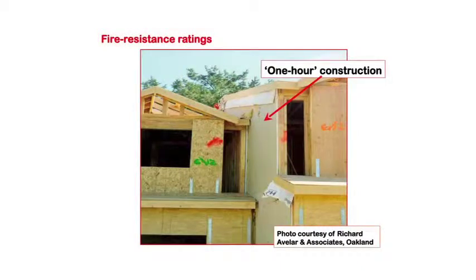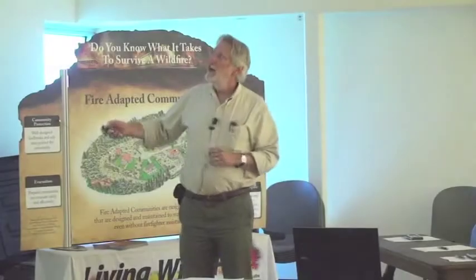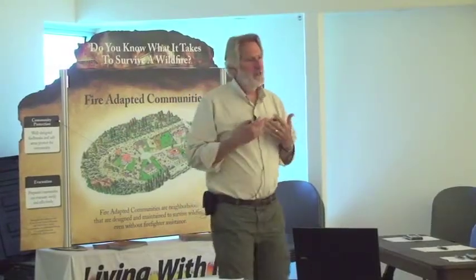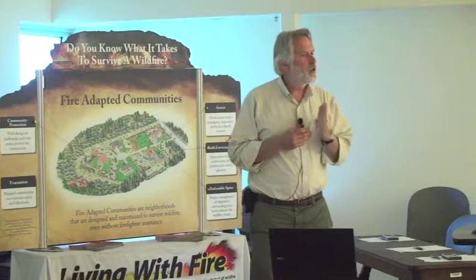Okay, so fire resistant. That was a term. Fire resistant is a term that's used most often for interior fires, and it's a way to describe how easily fire can move from one room to another. It's used commonly in apartments, condominiums, or townhouses where you want to stop fire from one unit from going into another unit, and this rating is often called a 1 hour rating or a 2 hour rating.